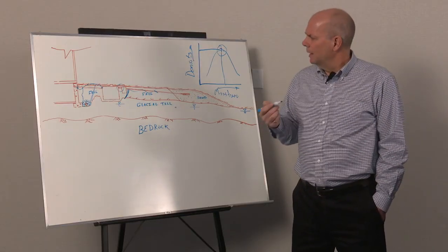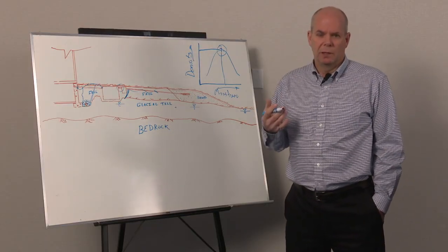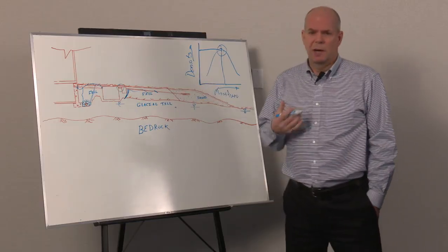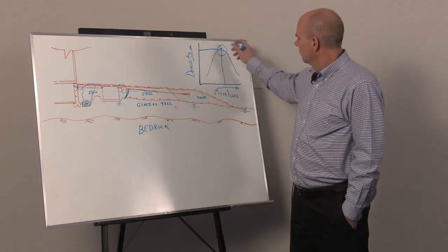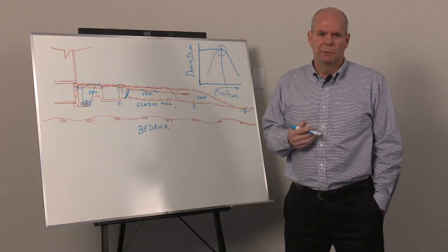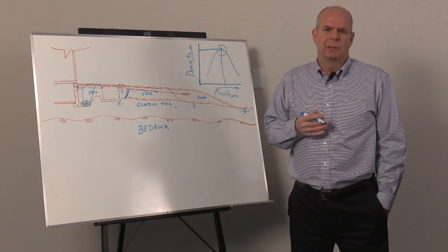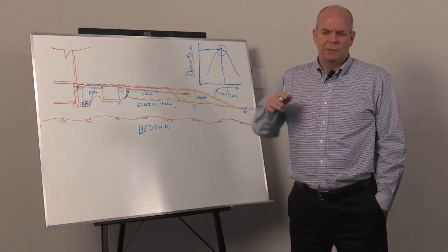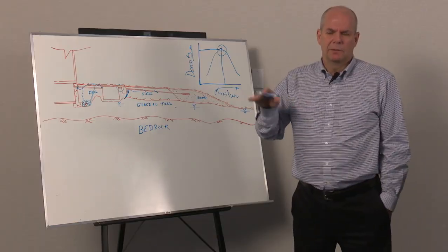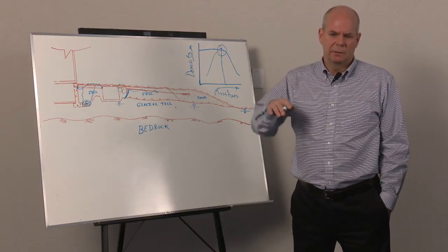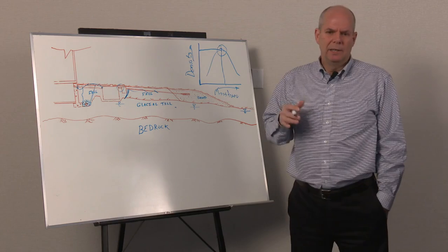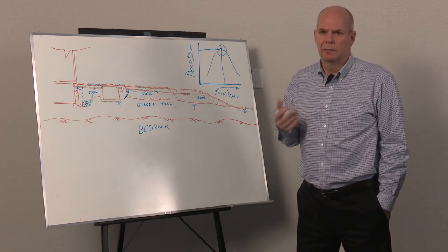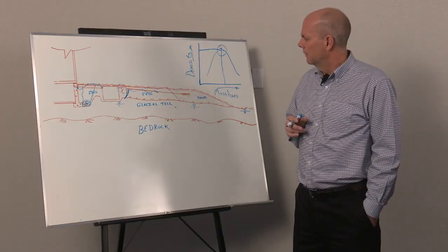And then when you dig back into it, if you do have a lot of dry material, don't use it in critical areas. Try and use a material that's at the right moisture content for workability. When you're dealing with the clay materials, you'll know you're at the right workability when you get a little bit of deflection off the clay as you're compacting it. It'll start to move a little bit. If it doesn't move and it looks like concrete, it's too dry and lumpy, and that can cause the problems that I talked about earlier.